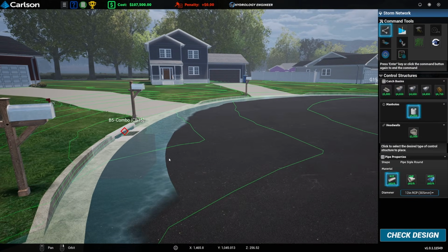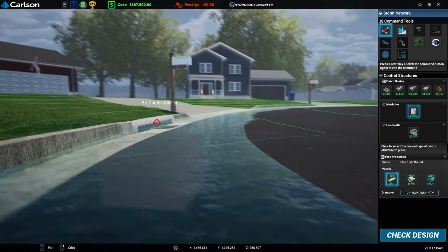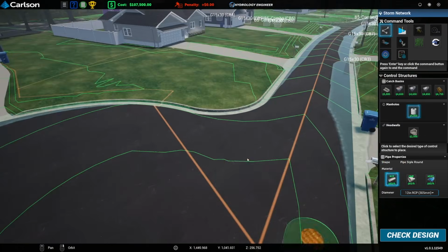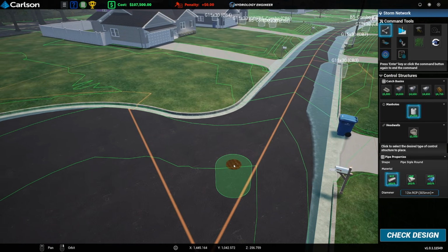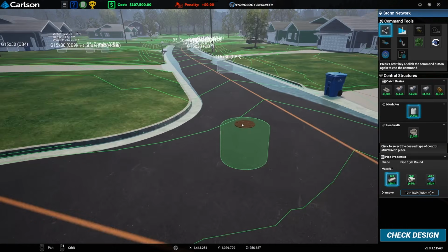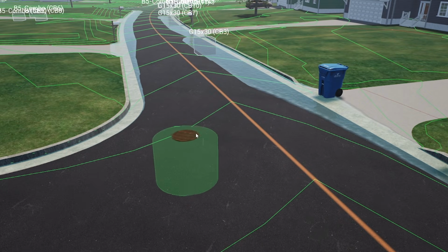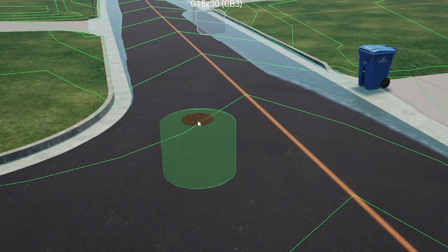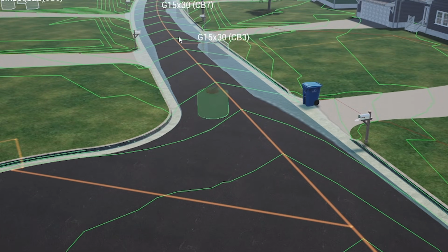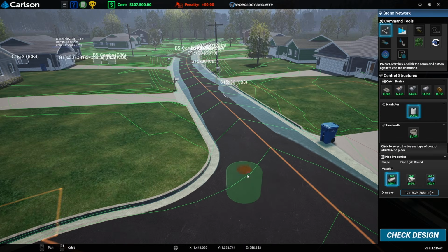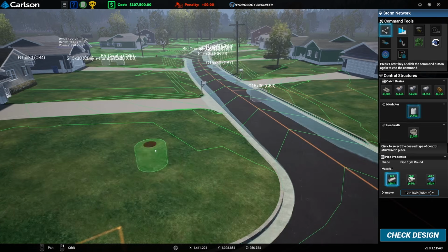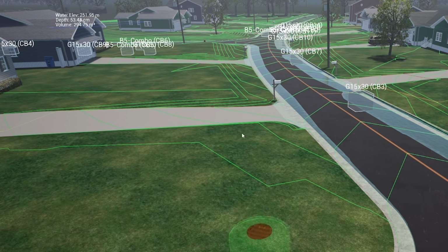The thing that's worth noting though is these gully pots are generally quite a lot shallower than these manholes. And these manholes, because they're going to be in the road, they're generally going to be about 1.2 meter depth, because at that depth you can have cars drive on top of your pipes without worrying about them getting crushed. If they were shallower than that, then the pressure of the cars driving on top would actually crush your pipes. And then that depth changes if you were to put your pipes just through a field or something, because you're not going to get cars driving over a field.